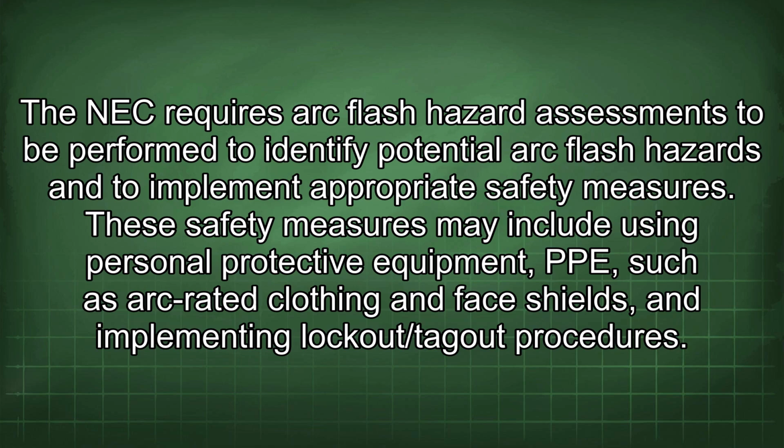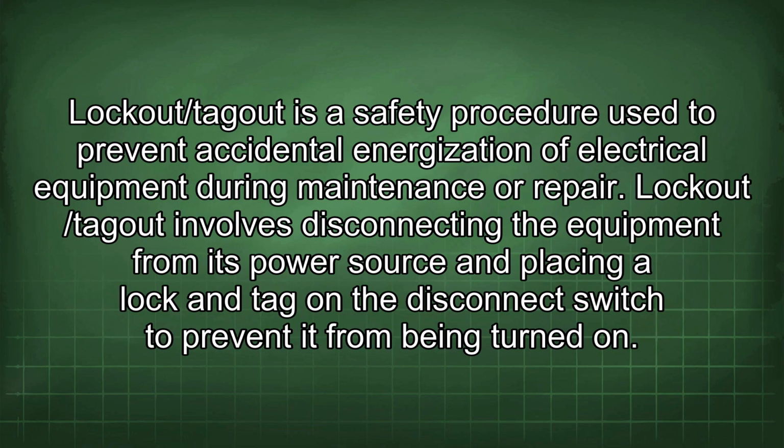implementing lockout/tagout procedures. Lockout/tagout is a safety procedure used to prevent accidental energization of electrical equipment during maintenance or repair. Lockout/tagout involves disconnecting the equipment from its power source and placing a lock and tag on the disconnect switch to prevent it from being turned on.